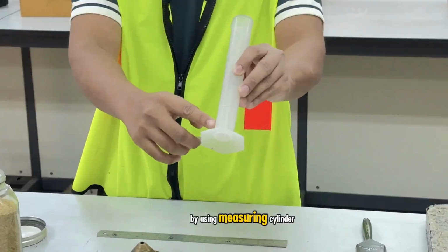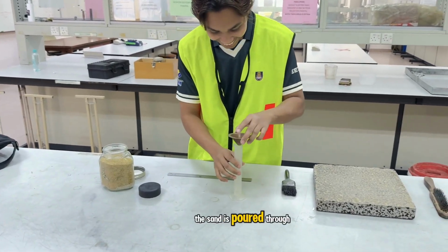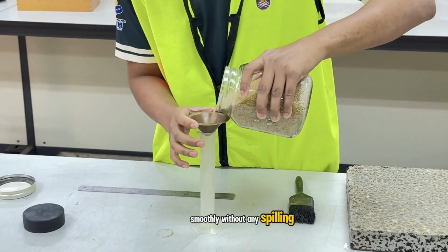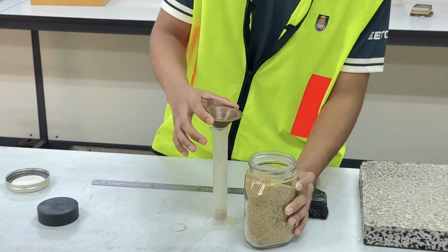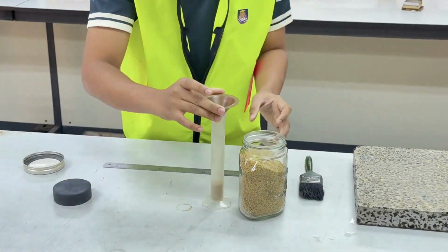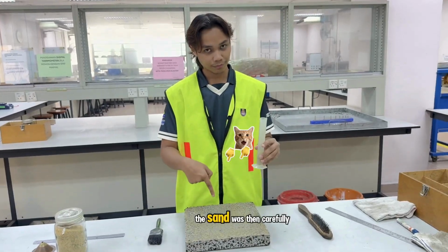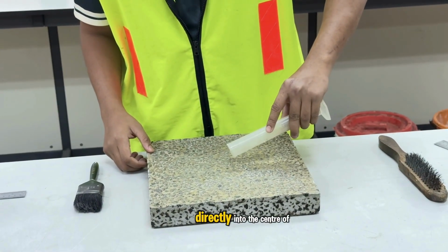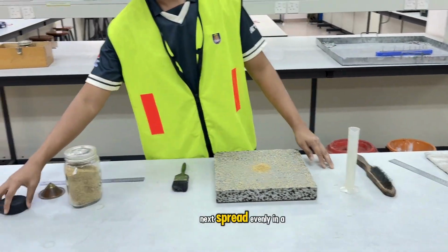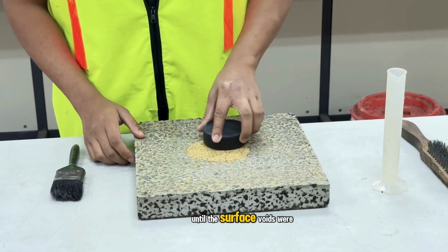By using a measuring cylinder, we take 10 ml of Ottawa sand. The sand is poured through the brush cone to ensure the sand falls smoothly without any spilling. The sand was then carefully poured directly into the center of the pavement surface. Next, spread evenly in a circular motion using the sand spreading tool until the surface voids were fully filled.